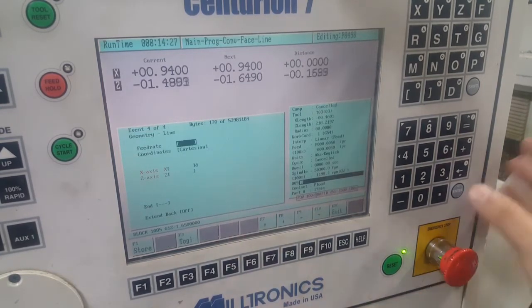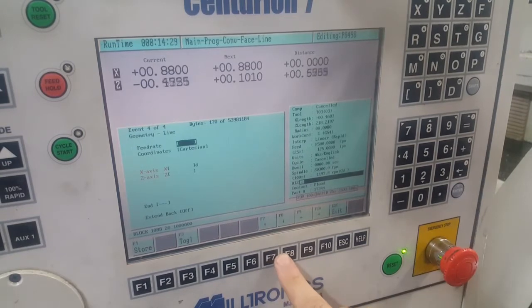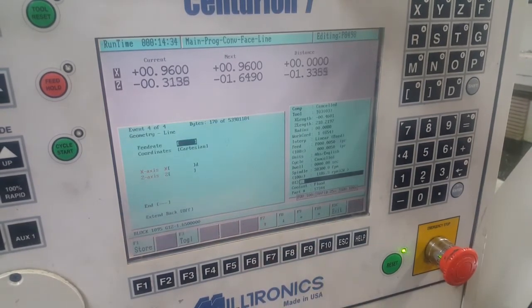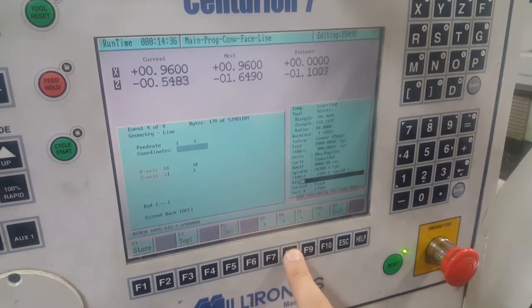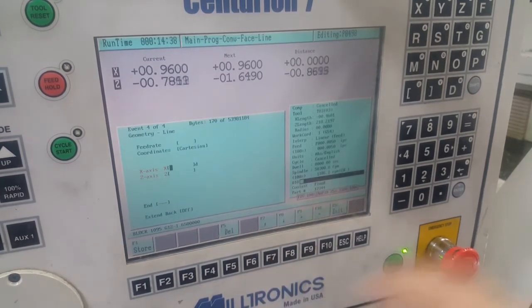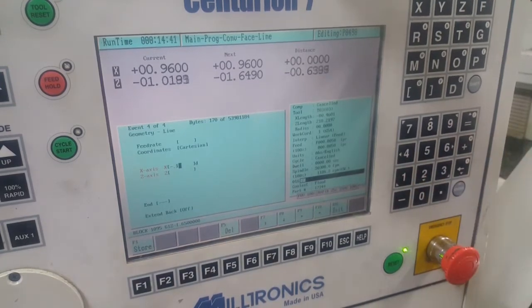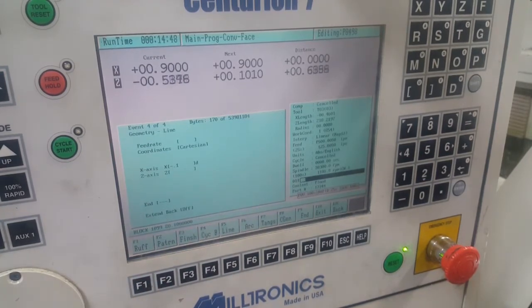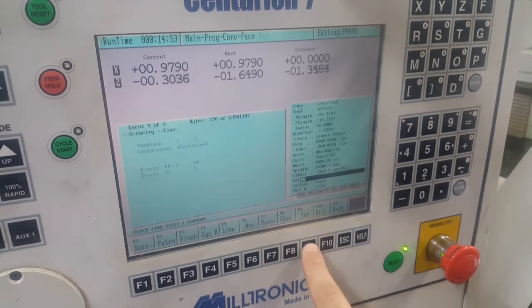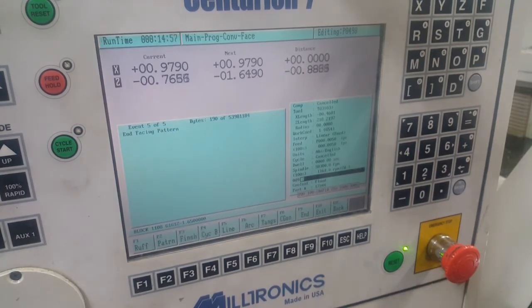We're going to do a line. The speed rate will be called up from whenever we call up our tool and we put in that feed per revolution. If we leave this blank, it's going to understand that we just want to stick with that. Then we're going to go minus 0.1, and that'll go past our center point, clean up the face of our part. Store. That's all we'll need for our spacing pass. So I'm going to end there and store that. Now that I've roughed my face, I'm going to finish.